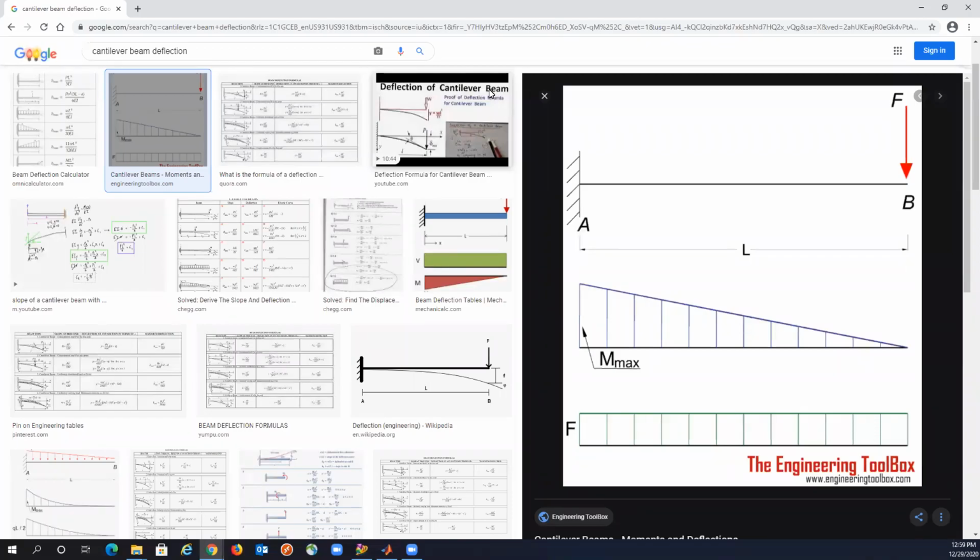Okay, so in this video, I'm going to try to make it short, but basically I want to show what the shear effect is. You will understand in a few minutes for a cantilever beam. So this is a cantilever beam. Due to that force, this would be the bending moment: maximum at the root, 0 at the tip, and the shear force is constant. All right.